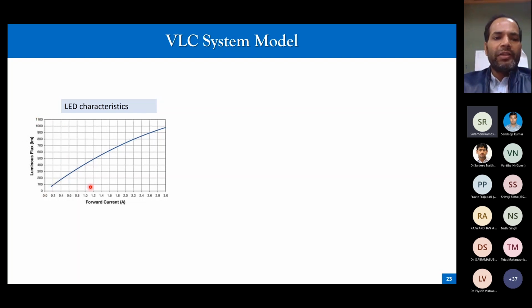So if we look at this chart, you know that an LED is a diode, right? You have a certain current flowing through this diode, and corresponding to this current, you have a power. This power versus current, or luminous efficacy versus current, or intensity versus current, you can use anything on this y-axis, is almost linear with respect to current. So an LED is almost a linear source, which is a good thing. We can say the power emitted by the LED is proportional to the current I(t).